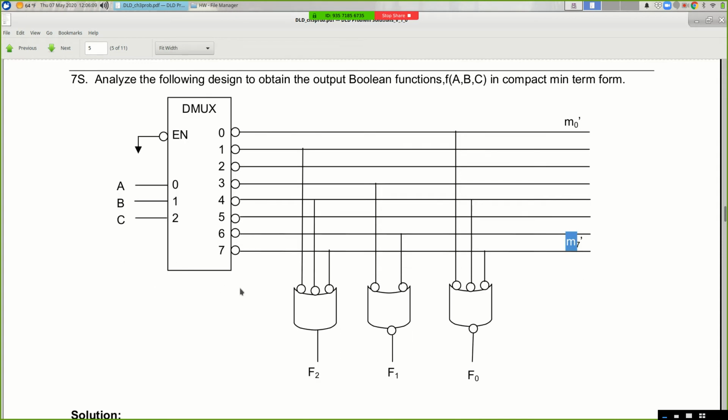So this is a fairly useful circuit, right? If we look at just the output F2, depending on your values of your inputs, all of these outputs are going to be logic 1, except for one of them. Now, if you happen to have an input value 0, 0, 1, line 1 is going to be the line that has a logic level 0. And if line 1 outputs a 0, that 0 comes down this wire, it goes through this inverter, and now you have a 1 going into your OR gate, and your output will be 1.